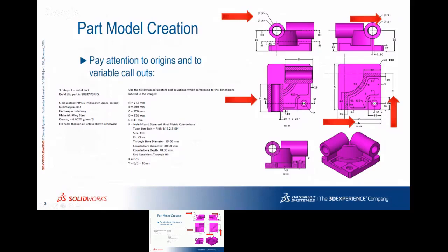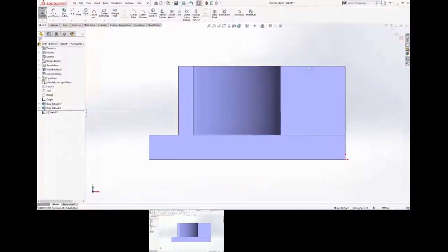If we look from the top view, it actually sticks out 10 millimeters, right? So I can create a plane, offset it 10 millimeters, and then reference that midpoint, right? But why go the extra step of creating the plane? It's another additional feature. Maybe it takes us 10 seconds, but at the end, how valuable is 10 seconds, right? It builds up. So again, I like to point out the tools to kind of help you get through these things faster. So let's create those bosses.